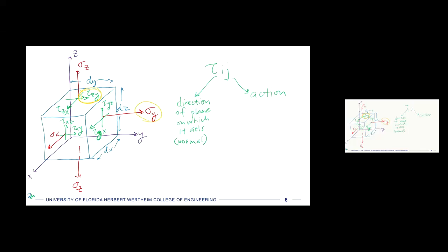If we have a stress state where the shear stress acts the other way, we can either draw it the other way or just call it negative. I think for the most part, we're just going to use signs to show the direction this semester. All right, so if we draw all of those on there, not including the ones on the back, because those are equal and opposite, we have 6 unique stresses to define the stress state.